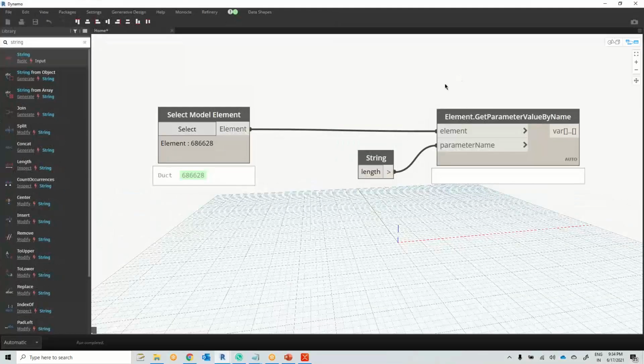So when you're playing with any kind of parameters, you have to remember that in Dynamo especially, it's case sensitive. It won't accept it if you make a mistake, like if it is lowercase L and you give caps, it won't return anything. In some cases it will show you a warning that there is no such parameter. I'll show you that later.